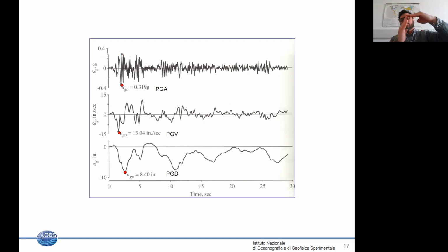This is in displacement. What is velocity with respect to displacement? It's the derivative. Yes. And what we said will happen to the Fourier spectrum if we want to go from displacement to velocity, how can we calculate the derivative of the original displacement spectrum? We multiply by i omega. Yeah, i omega.